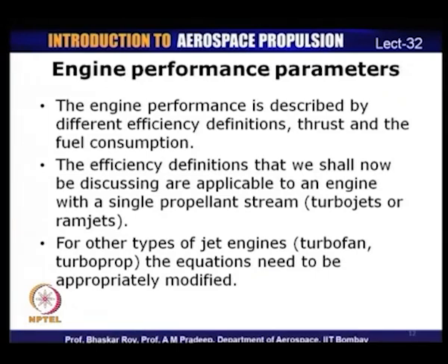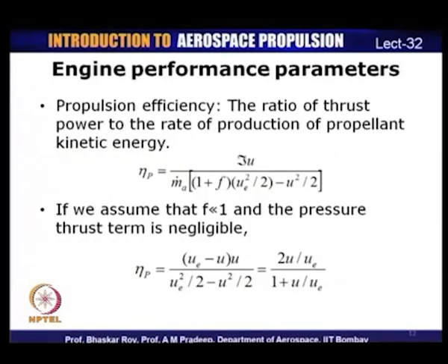And we shall now discuss efficiency definitions, which are primarily applicable to engines with a single exhaust stream, like turbojets and ramjets. For other types of jet engines, like turbofans and turboprops, the equations get slightly modified, but the basic definition remains the same. So, the first definition of efficiency that we are going to talk about today is the propulsion efficiency.